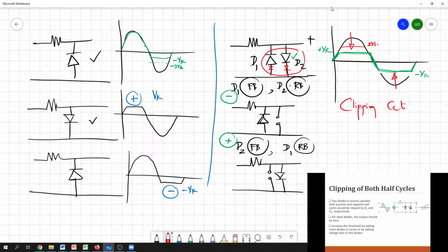Then you can simply obtain the equation for the output voltage by analyzing the circuit, because no diodes are there. You have resistors, sources, and either short circuit or open circuit elements in the circuit. So you can easily find the output voltage for the simplified version. Then you can draw the input and identify the regions, and based on these regions you can analyze the circuit and find out the output voltage.